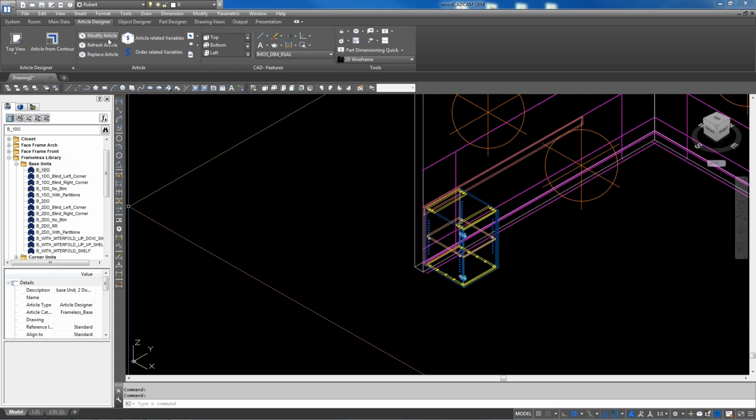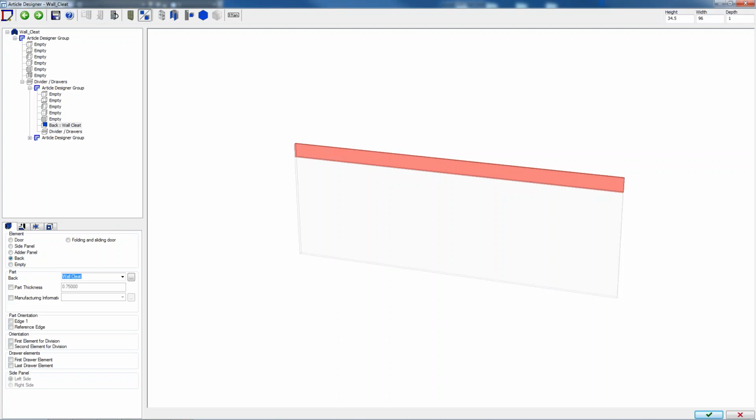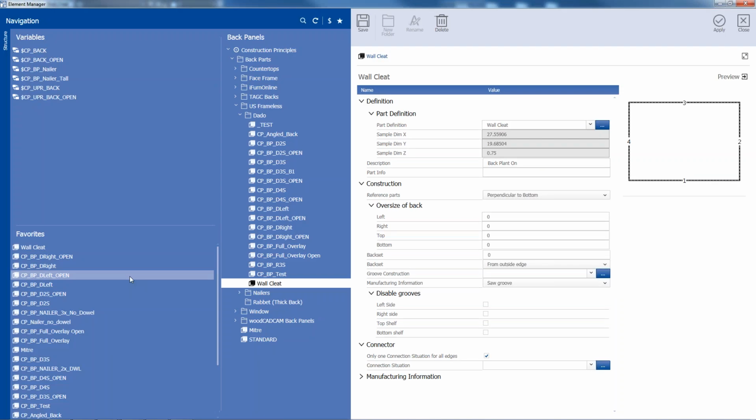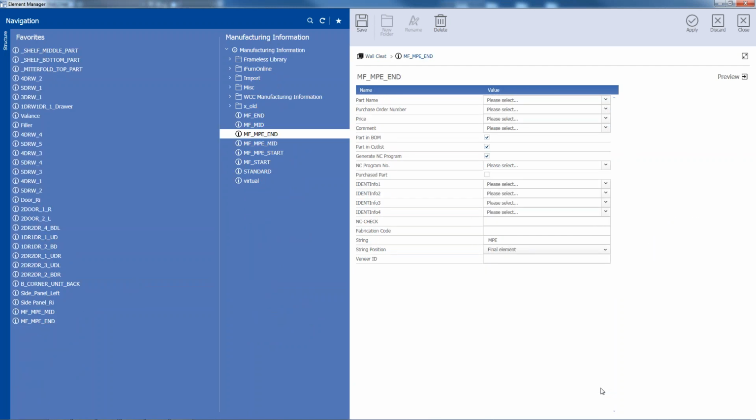Okay, so the only other thing you'd want to do is... That's right, but having this article now, we could, let's say, include it to the cutting list. You just specify whatever size you want there. If you don't want to cut it, then right here in your manufacturing information, you can assign a virtual part so it doesn't get sent to the cut list.